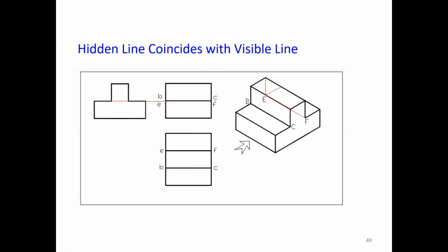Do remember. Also here, this one also hidden line, this one as well as this one. So this one is also hidden line. But this is also overlapped by this particular line. So that's why it is also required to draw by visible line. Getting? So this is what the concept of hidden line.